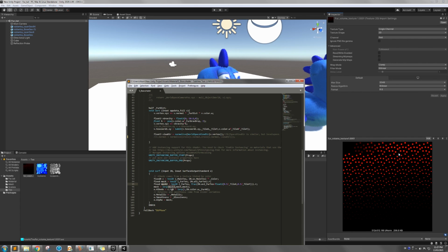Imagine this one section is filled on the full UV space, 0 to 1. So 0.5 means I want to offset half the size of this section, so the fur will not overlap. It's like you duplicate this texture and offset it, making more fur density.